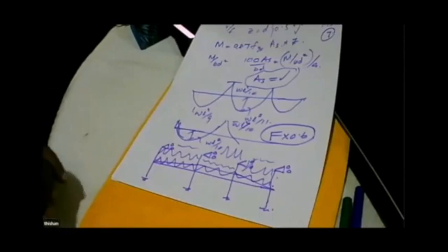So somebody says, okay, I'd like to find the shear. So I find the maximum load multiplied by 0.6. That is the shear force. If somebody asks, what is the shear? I say, okay, it's 0.6 times the full load. On the other hand, I can find it from the bending moment diagram. The model is there, so you can find the shear force. Is that clear, Bandhu? Yes, sir. Clear.